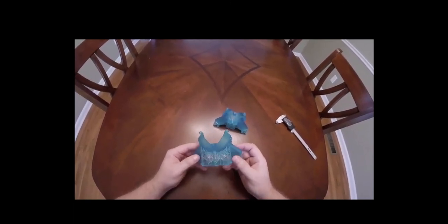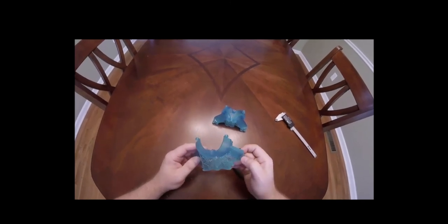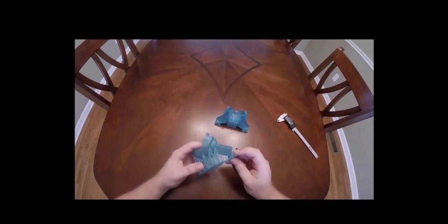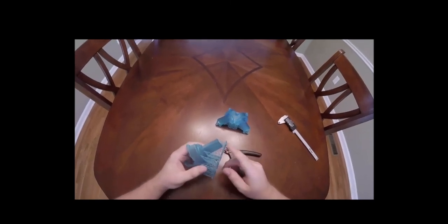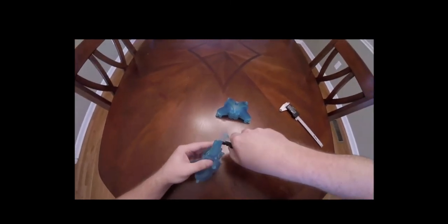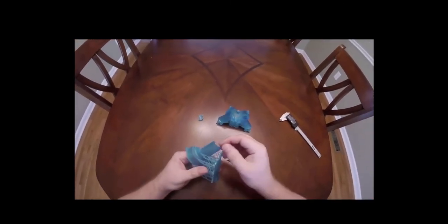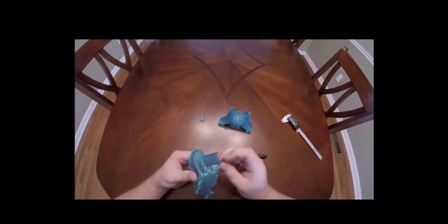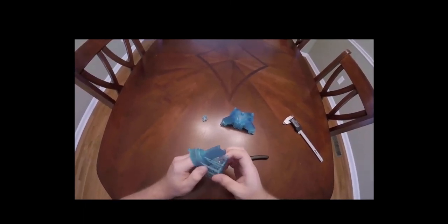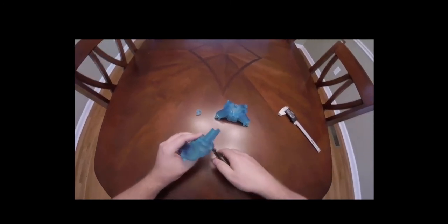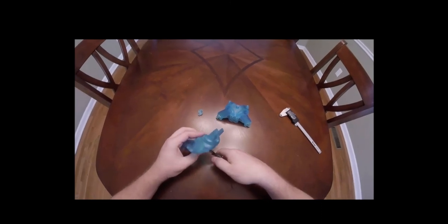For this model, like I said, for the most part, I'm going to be fatiguing and breaking the supports off, and you'll see the process I take. I'm going to start at this end of the part, and I'm just going to clip the base so we can remove that part separately, and you can see the whole thing just fell off there, which is great. And there's very little mark left from the supports. So we're just going to go through the whole part with that mentality and get all these supports off here. So I'm going to crack the base in a few places.